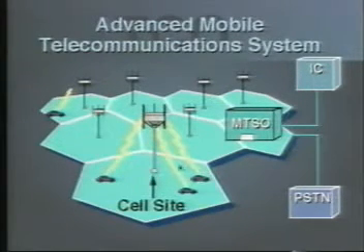So what we do is we set up an area. In this case, it's called a cell. It's sort of a multi-shaped, many-sided area within which this transmitter is able to pick up and send telephone messages. It then transmits back to another central office, only this one's called the Mobile Telephone Switching Office, and it provides the connection between this radio telephone link and the physical wires that go back into the regular part of the telephone network.